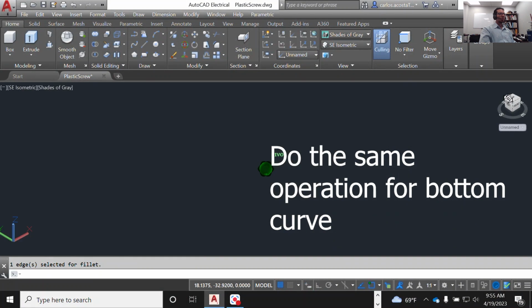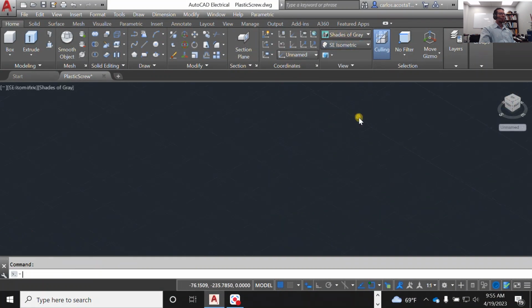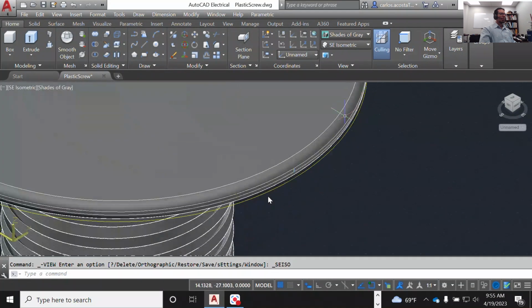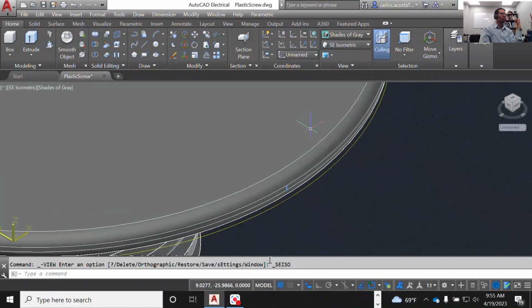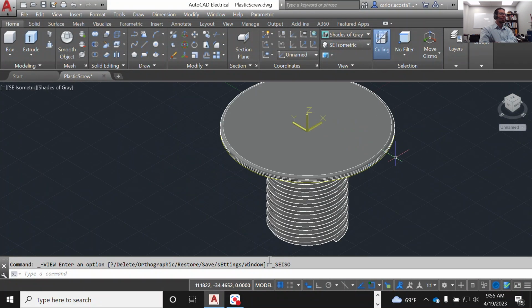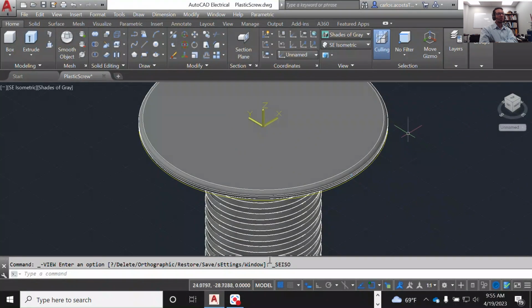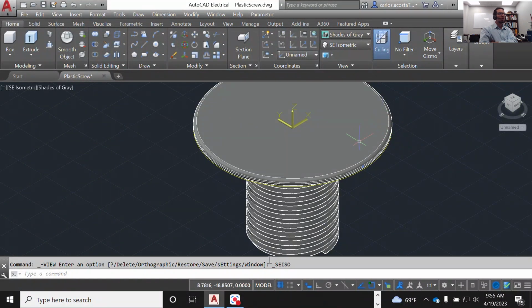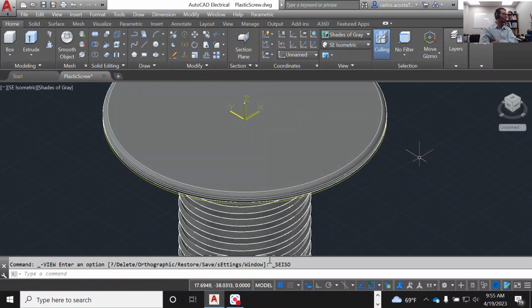Okay, so if you notice, and go to isometric view, we have our edge with our radius, which is pretty much what we want, and you can go back and maybe if you want a more aggressive radius, you can choose 1.2 or just check the radius to the point that you're comfortable with. And it's also manufacturable, like it's easy to do. Or if you use a 3D printer or something, that will be within the tolerances of your printer.